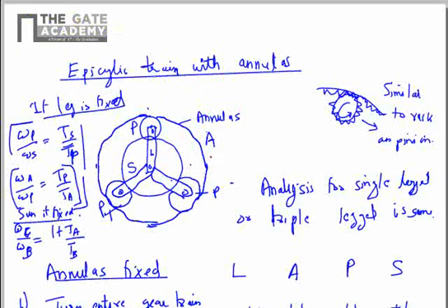So now since A is given -1 revolution, that is anticlockwise sense, so what will be the angular velocity of P? Since A is moving in this direction, P will also move along this. As you can see, if A is moving in this direction, the direction of movement of P is same as A. So P also moves anticlockwise, and the velocity ratio is from this relation omega A by omega P is equal to Tp by Ta.